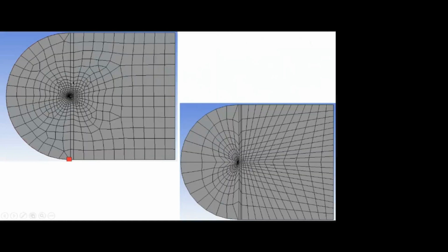Then you can go for the mesh. Initially, if you import, you'll get unstructured. Then using face meshing, you can get the structured. Then we can do the further refinement towards the airfoil. That's what we're going to see here. So we will start with downloading the coordinate points, then importing, creating, etc. Any doubt in this?